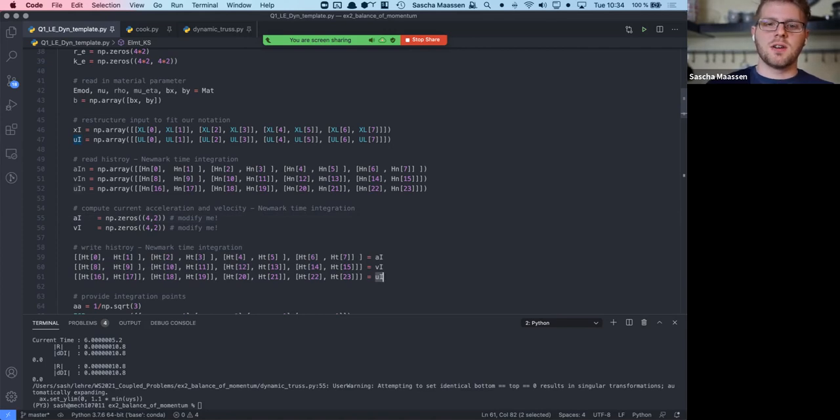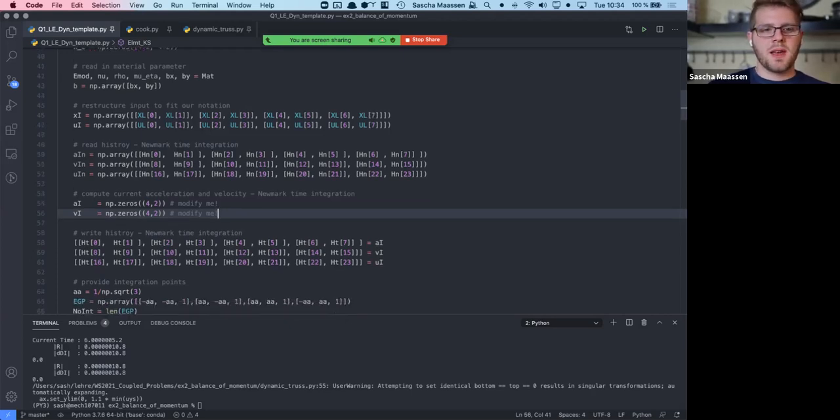This structure you can easily see from the single mass oscillator problem as well. You already see here the first task that you guys have to do today, implementing the Newmark time integration for achieving the nodal acceleration and velocity. Everything else regarding time stepping or time shifting of those variables will be provided by PyFEMP.